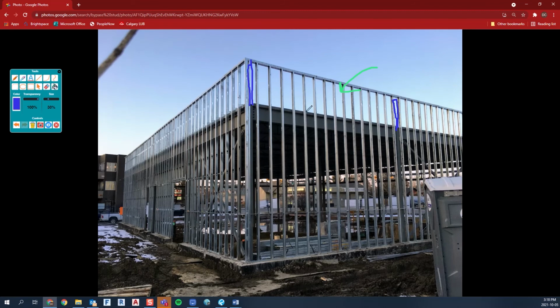And there might even be other posts put in here as well, steel posts put off the top of the beam. So if it was an infill system, then the stud would be stopping at the underside of that beam, and you'd put in your studs in an infill system. And then to build that parapet, you'd build a stud wall above that beam, essentially.